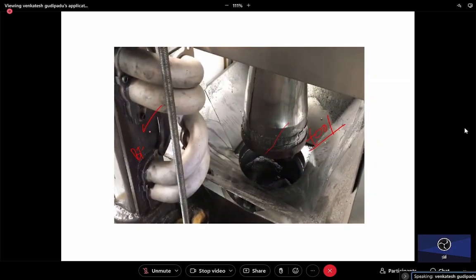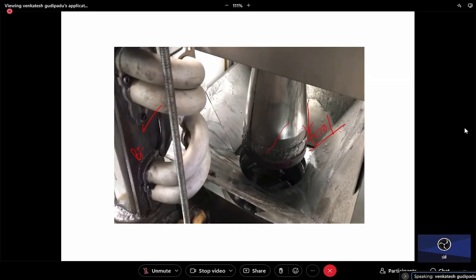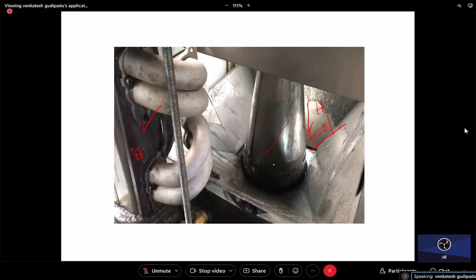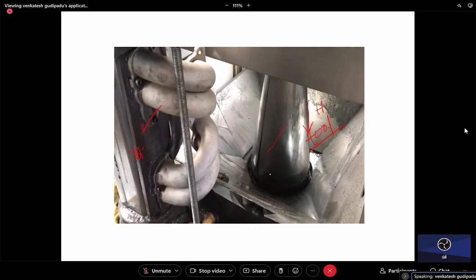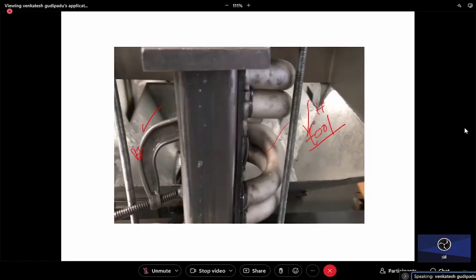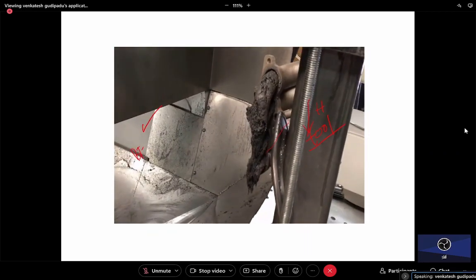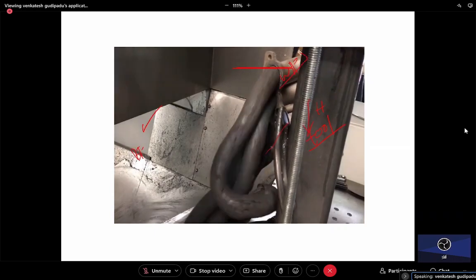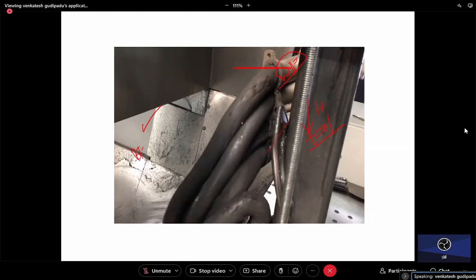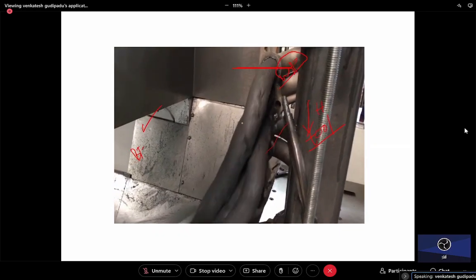Now you can see we are pumping this semi-solid medium by hydraulic pressure. This is a hydraulic cylinder I'm talking about, right? We are pressurizing the medium to flow through the target surface. What is the target surface here? My target surface is the manifold, right? You can see the media is coming out from this. This is my workpiece, and the media is flowing through the workpiece by radiusing it, by deburring it, by removing the burrs, and also by finishing the workpiece.